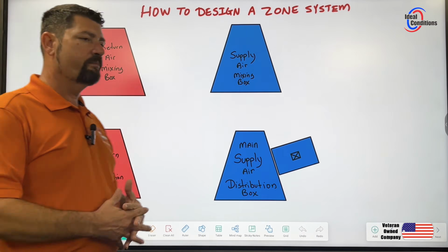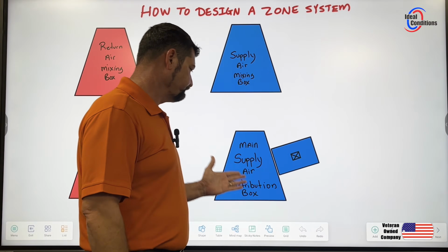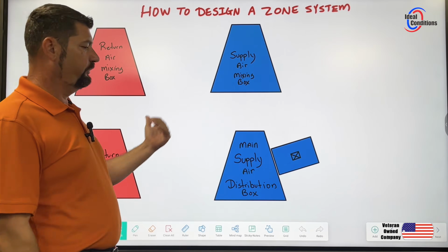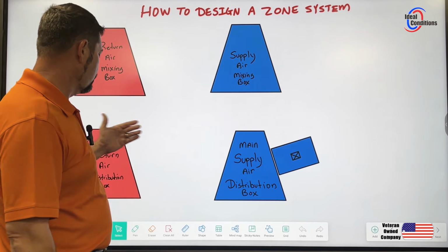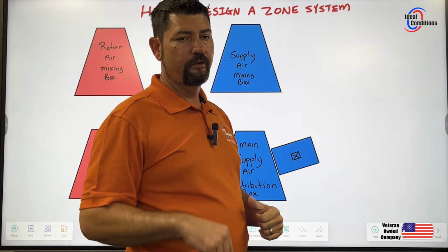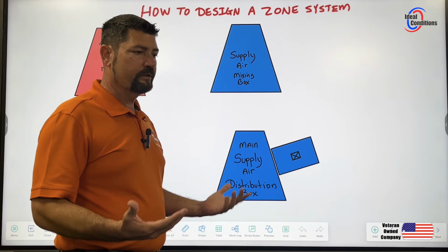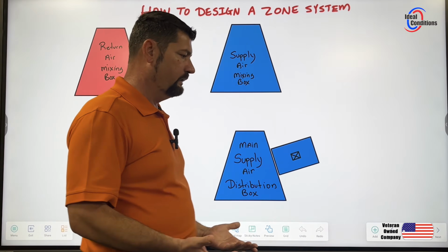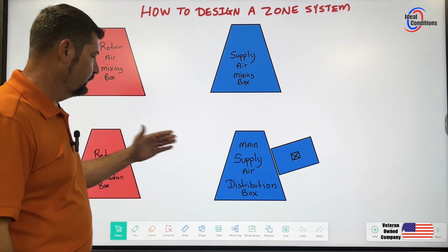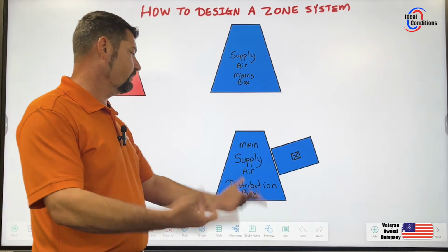Because we have to involve bypass ducts. A bypass duct is basically a damper that opens based on static pressure to allow air back into the return side so it can circle back around and not cause excessive static pressure buildup that can hurt motors and potentially lose compressor oil inside the compressor because of not enough airflow on the evaporator coil.